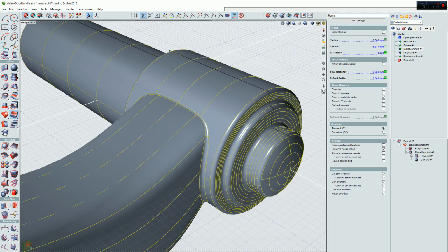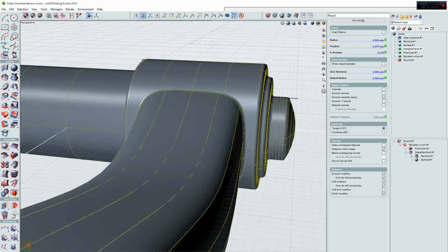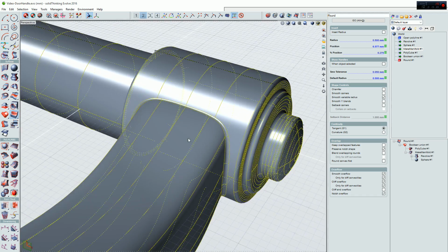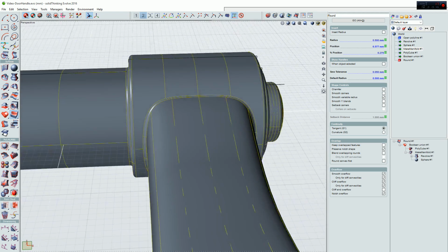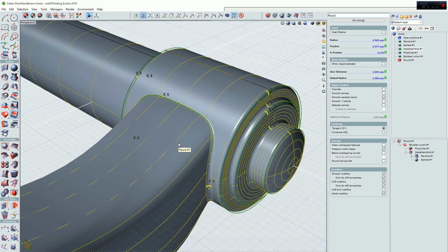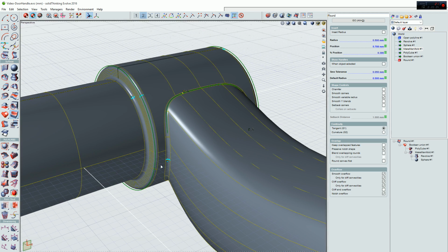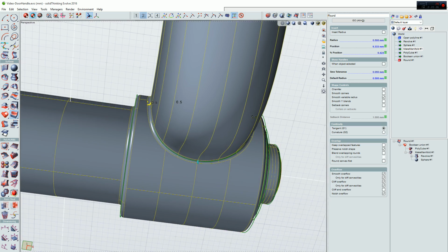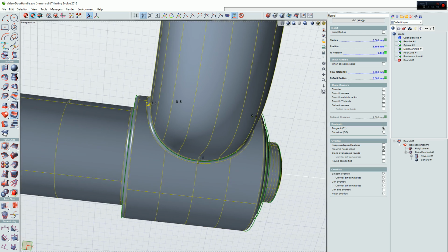And you see they are well rounded now. Everything is very smooth and very nice. But I want to have a bigger radius over here, because here I have much more space around, so I can have a smoother connection between the two parts. So I go in editing mode for these two. I select the edges here, all the edges around, all the radii around this edge.